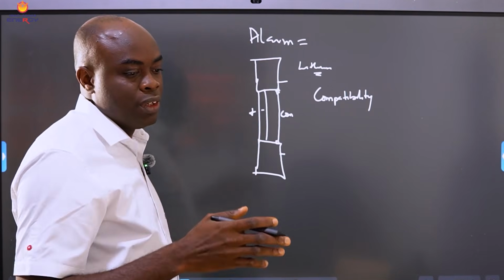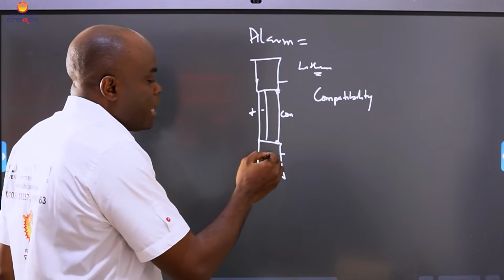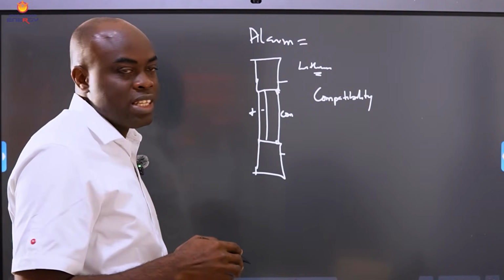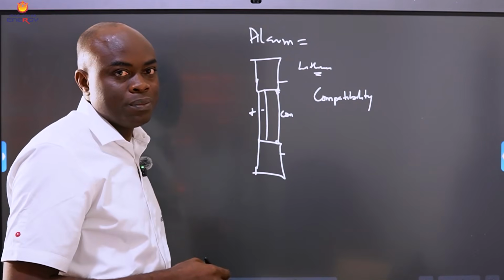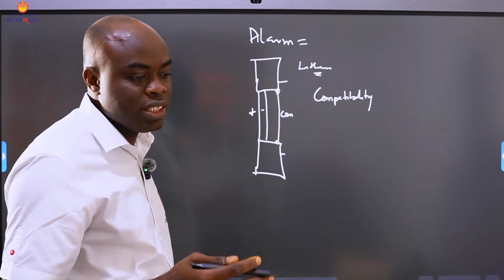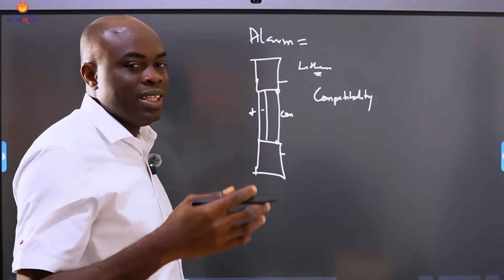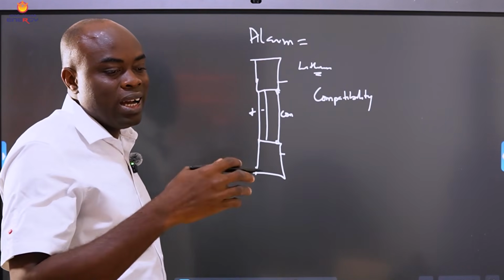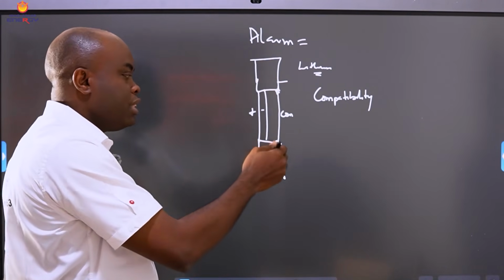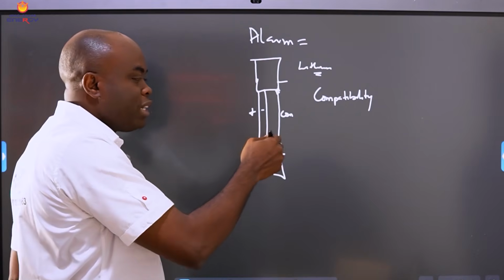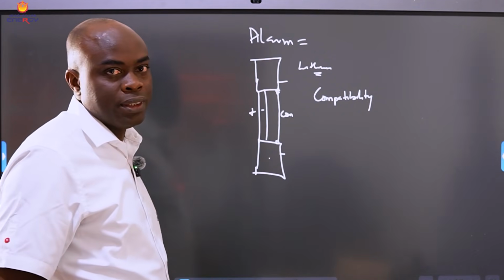Because if I sell, it means that your warranty is void. Because the battery is going to fail as a result of no proper communication based on its parameters: its charging voltage, charging current, the depth of discharge recommended, the temperature it should be operating in, and other information that the inverter you are connecting should pick from the battery to be able to manage the battery lifespan.